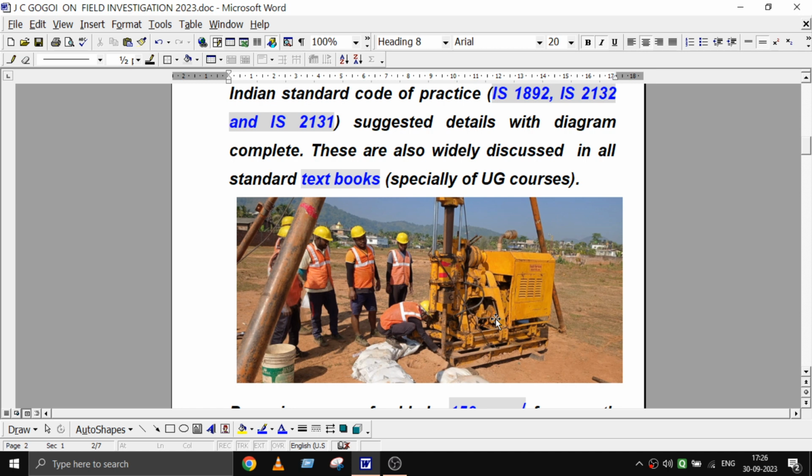It can be rotated manually and gently using mud water. Normally here also we are using 5% bentonite clay, and that simplified boring also uses 5% bentonite clay. Percussion drilling, however, is not allowed for investigation purposes, because this pressure